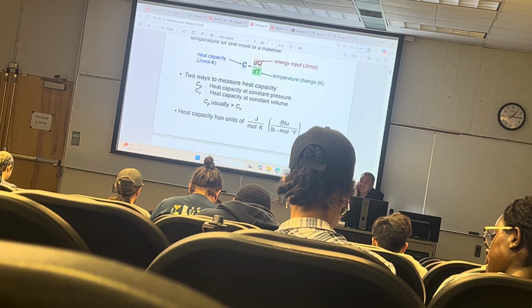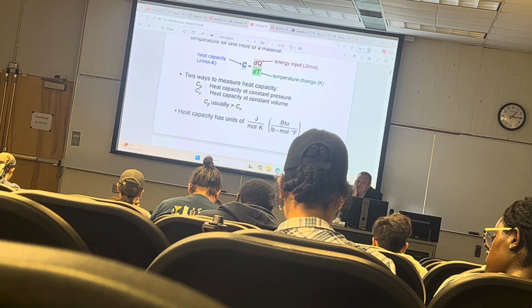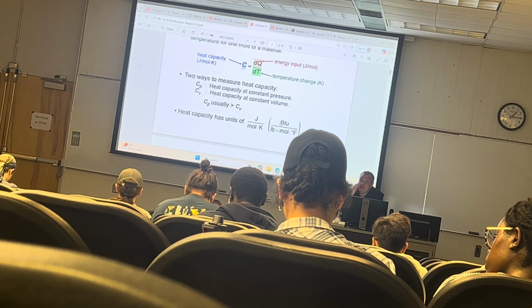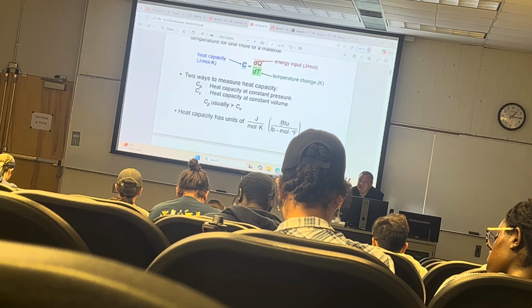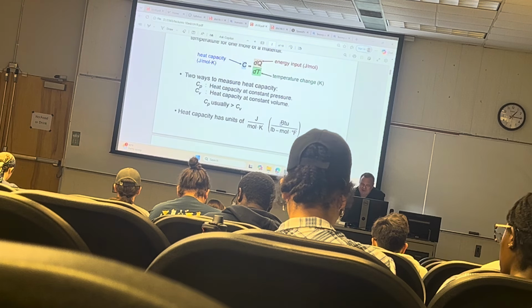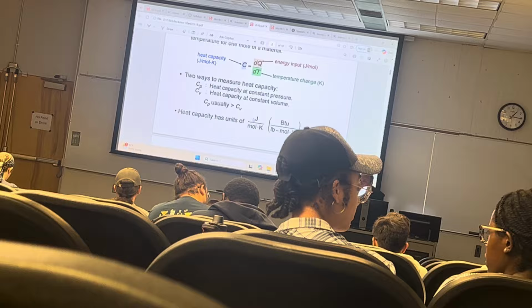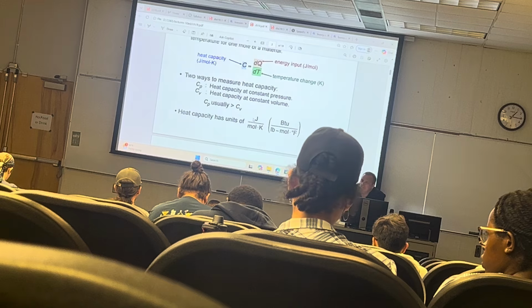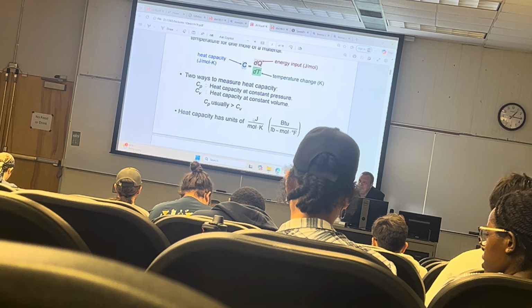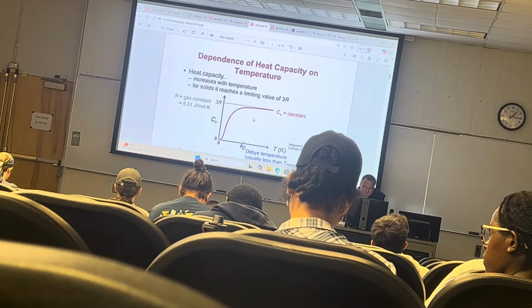No, it's 12,000 BTUs. 1 ton is 12,000 BTUs. So 1.5 tons is 18,000 BTUs. 2 tons is 24,000 BTUs. But if you go to Europe, they're going to give you the same thing, but in joules. And because I live in the United States, I know what a 2-ton AC is and what a 1 ton is.